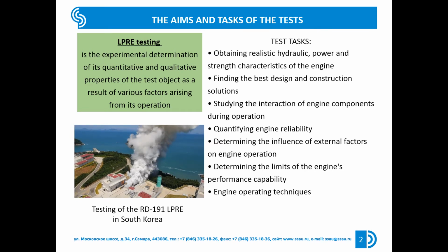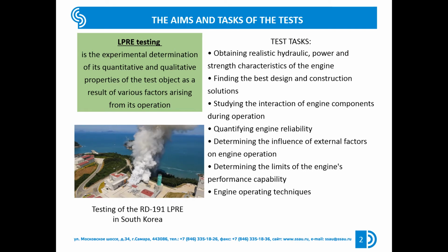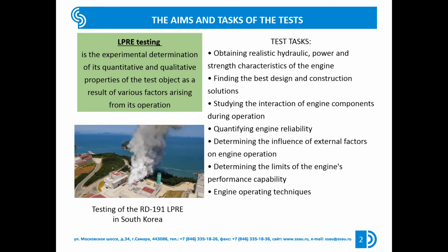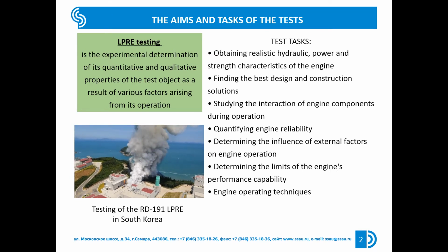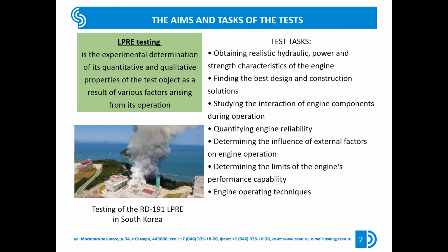During the LPRE testing, the following major tasks are solved. Obtaining real hydraulic power and strength characteristics of the engine under different conditions. Finding the best design and construction solutions. Studying the interaction of engine components during operation. Quantifying engine reliability. Determining the influence of external factors on the engine operation. Determining the limits of the engine's performance capability. Engine operating techniques.